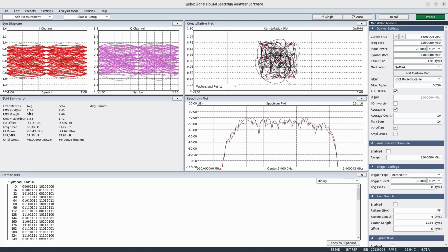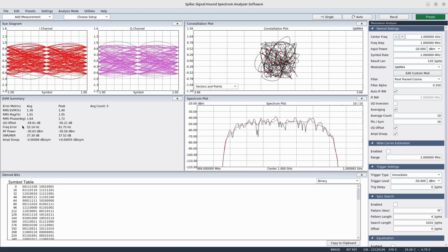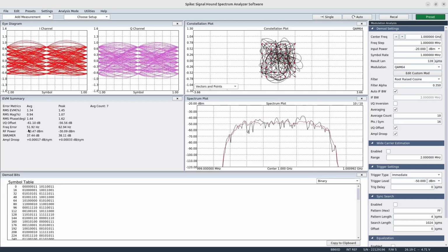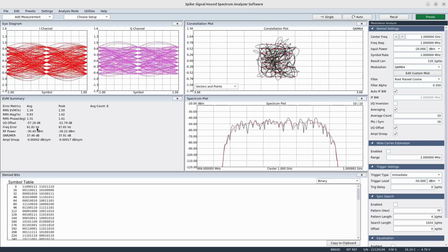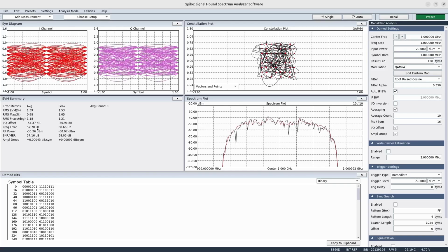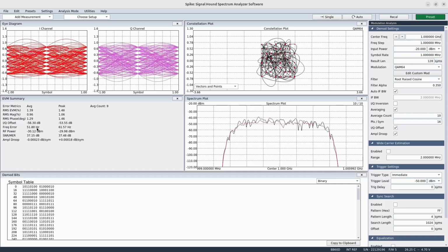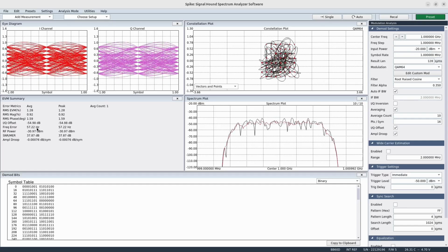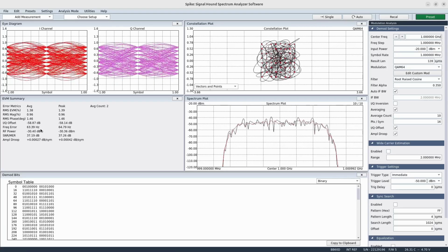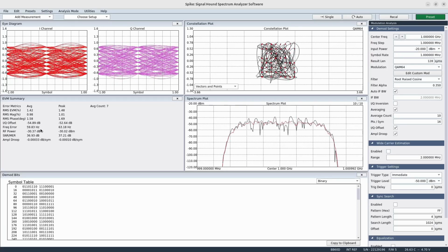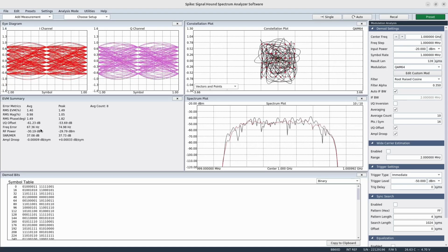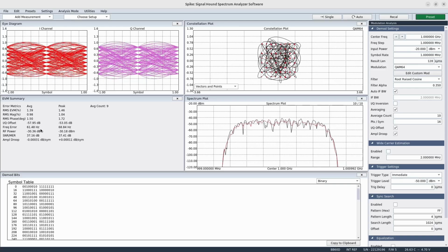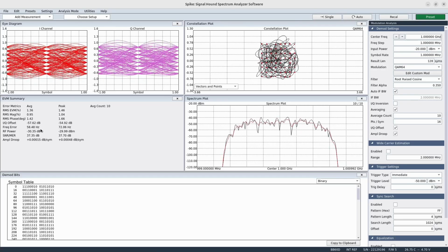And so like that, as you can see here in SignalHound, with the average value, you also have the ability to see, for example, what the frequency error is in here. The average frequency error is 50 errors here. So yeah, for a device that is a little bit more external to a computer, a device that is not directly bound to a computer and the tablet, the frequency error also appears a little bit lower than the tablet itself. But I may show you another video where the devices are also synchronized with the clock, where the frequency error with Harogic is lower than that.